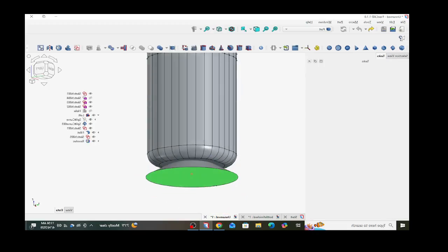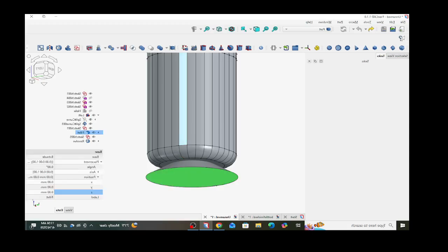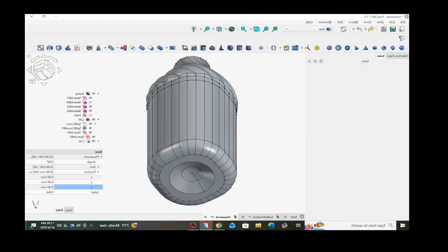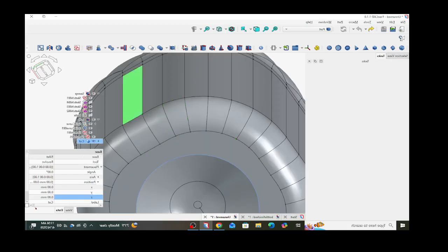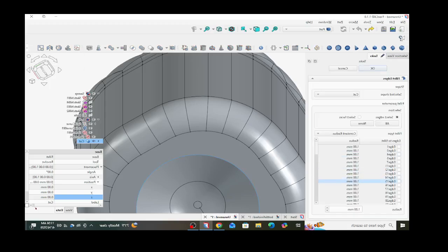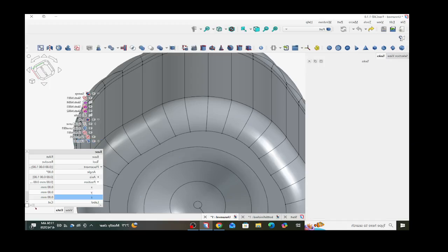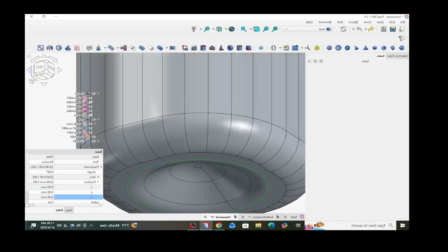Click OK. Alright, perfect. That's exactly what we want. Click first on our fillet and then on our revolve. I'm going to perform a cut. And I'll be filleting this inside radius of, we'll see if 10 works. Works just fine.